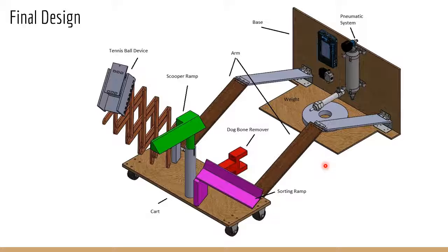Of these mechanisms, only the cart deployment mechanism and the scooper mechanism have been tested. Preliminary results show that the cart mechanism works well, except that sometimes minor variations in the manufacturing of the arms can cause the cart to torque slightly to the left or right when the mechanism is deployed. Also, with the scooper, we found that it works well at sorting the gems, except when nifflers sometimes reach under the scooper, causing gems and nifflers to fail to ingress.